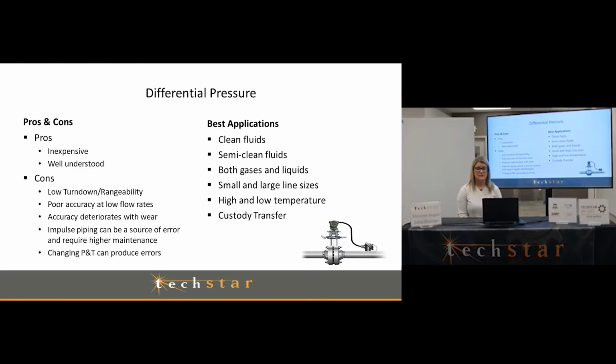Clean fluids or pretty clean fluids are the best application for this. It can measure both gases and liquids, which is a positive to this measurement. And it has a really good range of pipe sizes. So you can do very small lines or very large lines, depending on what your primary element is. And it is very flexible for temperature. Normal temperature ranges, something that you can touch without freezing or burning yourself, to very, very hot applications and very cold applications. Differential pressure can do all of that, so it's very flexible.